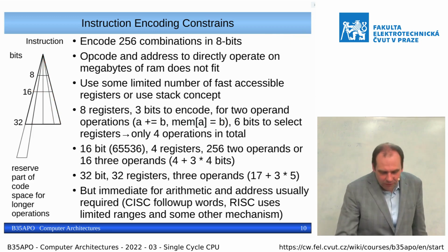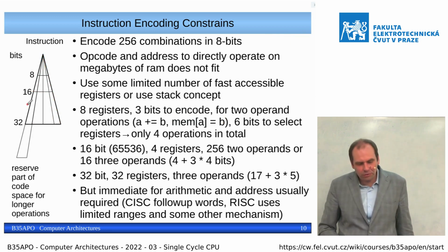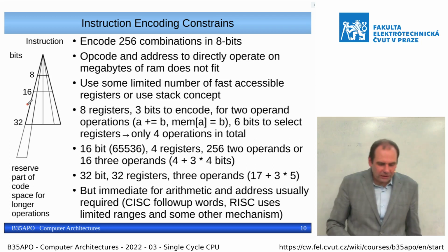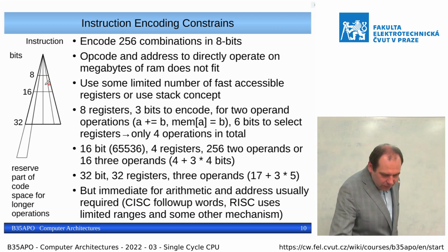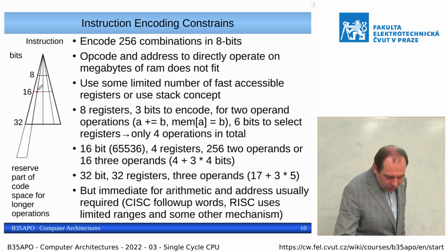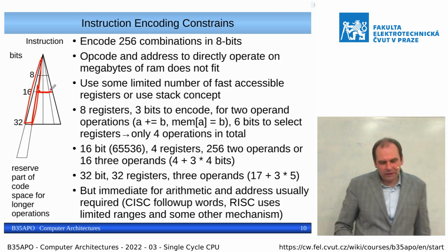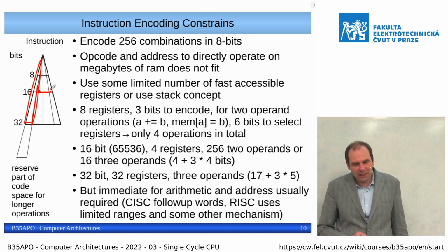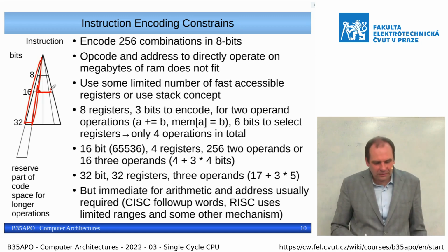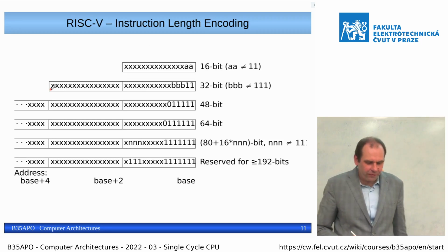But sometimes it is worth having such solutions. For example, on RISC-V, they decided that they would use only 1/4 from the 16-bit area and leave the 3/4 to store shorter aliases, 16-bit aliases. So this allows increasing the density of the code. So it is the idea from RISC-V.